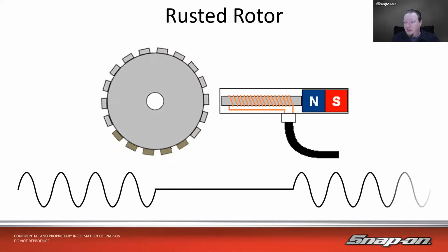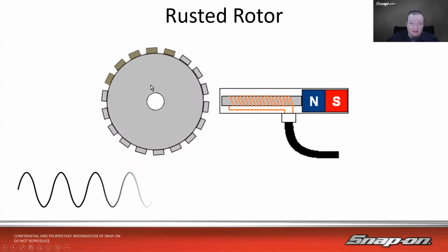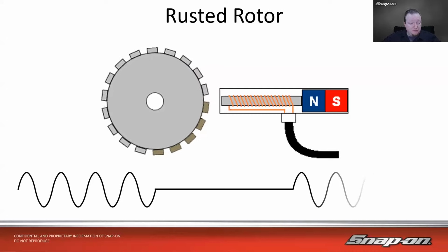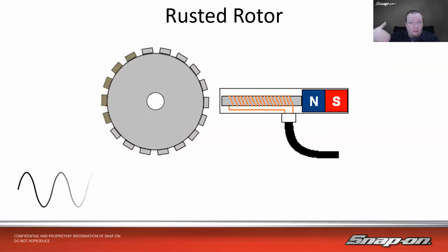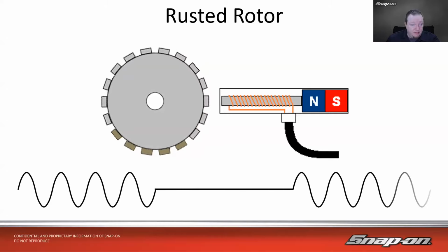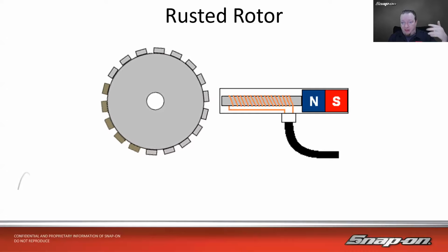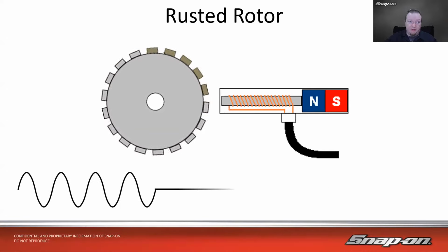It took them a little while to figure out, but what they found was that on the ends of the axles, it had those tone wheels, and one of them got really rusty just from being in New England. That's a problem up here. So it would cause a dropout in the signal, and all you have to do is replace the tone ring or what have you, and that's the problem.